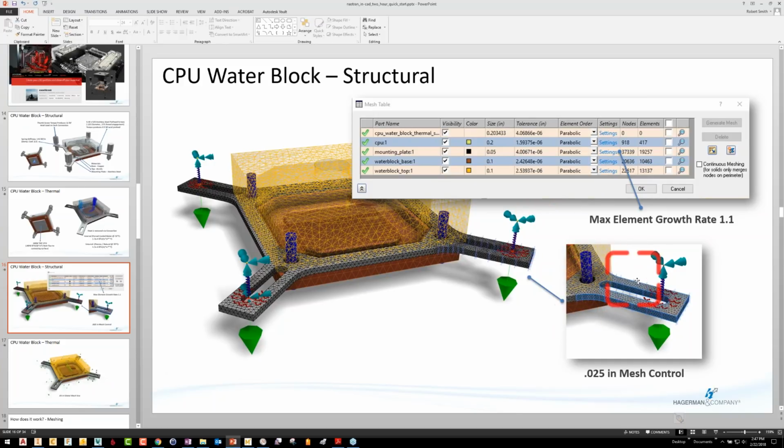And then I'm going to put a very localized, even finer mesh on just one of the tabs, assuming that they're all going to be representative of each other. I don't need to refine them all. I'll just refine the one and see how that does with that final small mesh. So you can see what a local mesh control looks like as well.